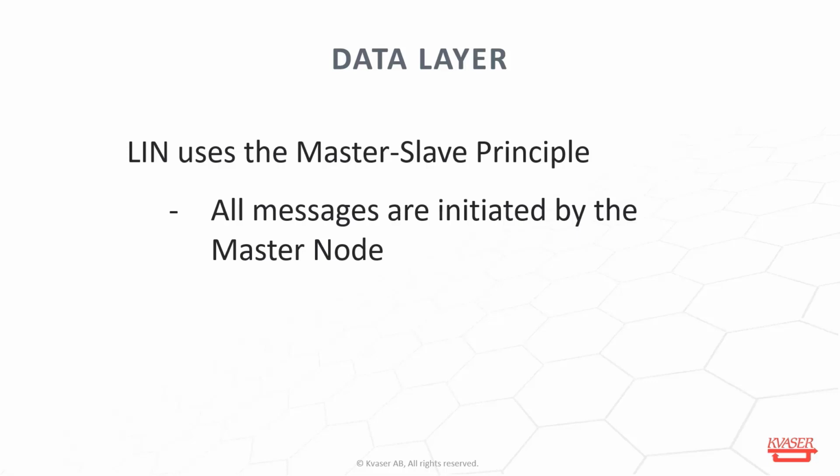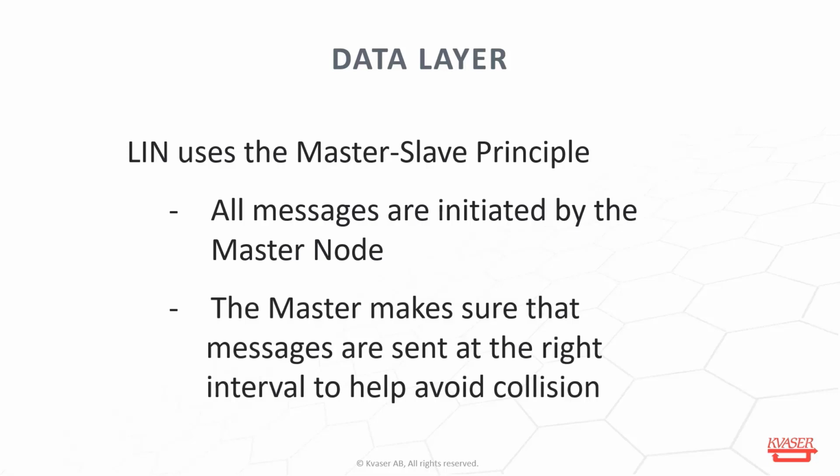All messages are initiated by that master. The master sends data out or asks a node what's going on, and the node replies. The node itself won't put a frame out on the bus on its own. The master also controls how messages are sent. That will allow for better control to avoid collision. The master will set the timing. It will tell the nodes the speed of the bus so that the slave nodes themselves will auto-baud to what the master wants.